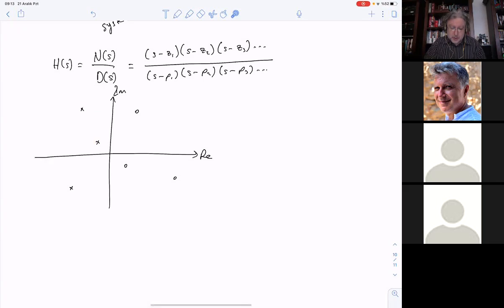By the way, by looking at these poles and zeros, I can see that they are not in reciprocal conjugate pairs. So that's a bad thing because it means that this H of s is a complex valued filter. That's not very physical. If you want to have a physical filter, you should better put a 0 here, for example, then its conjugate, which is here, must also have a 0.